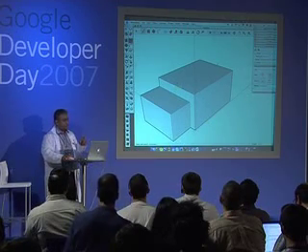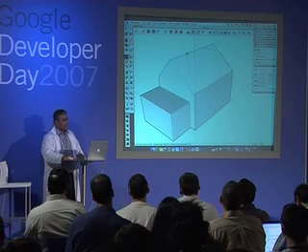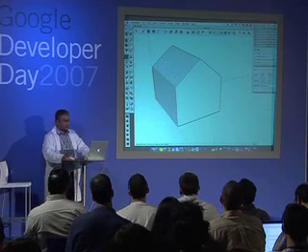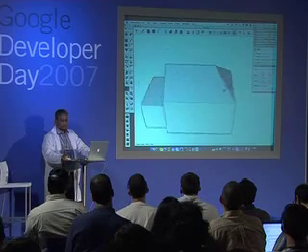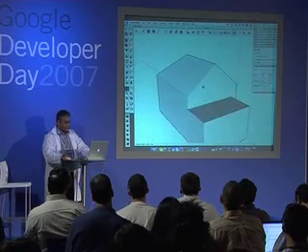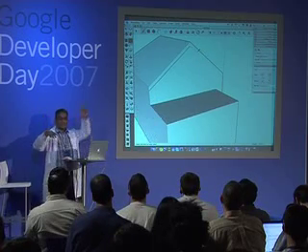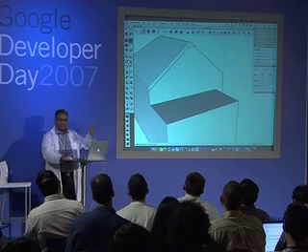So I'm going to put a roof in here, midpoint to midpoint. I use my move tool, and I will just pull that line up. Okay. I don't want that to be straight. I will actually choose a fold line there, use my move tool again, and push that back. Okay. Let's put some detail here. Again, I want to draw a line from here, parallel to this line, vertically down from that point. There you go. It automatically refers to these points on the drawing, allowing you to carry on with your design. You don't think about the software.